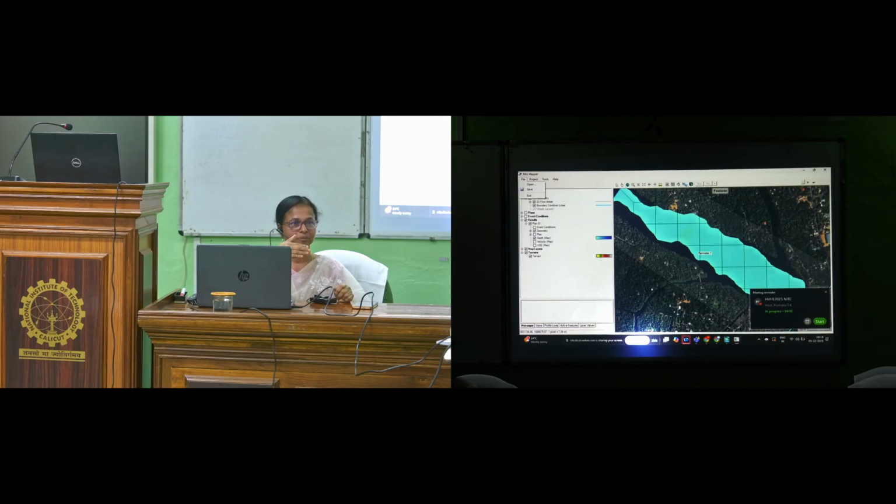That is what the one-dimensional model is, you can do it yourself, very easy. Whatever I have mentioned, from upstream to downstream, you have to digitize the river center line, then give the river boundary lines, then the floodplain boundary line, then give the cross sections. That is the main geometry here. Then give the boundary conditions, then run the model.